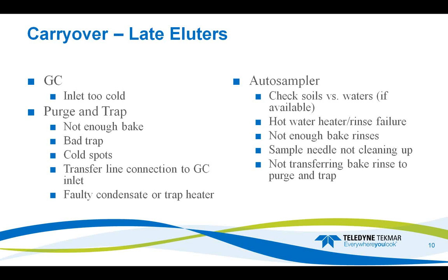On the autosampler side, again, if we have the option to do an in-vial purge, we can run that and compare it to our water purge. Or if we're doing in-vial sample purging and we're seeing carryover, we can run a water purge and see if we also see that carryover.